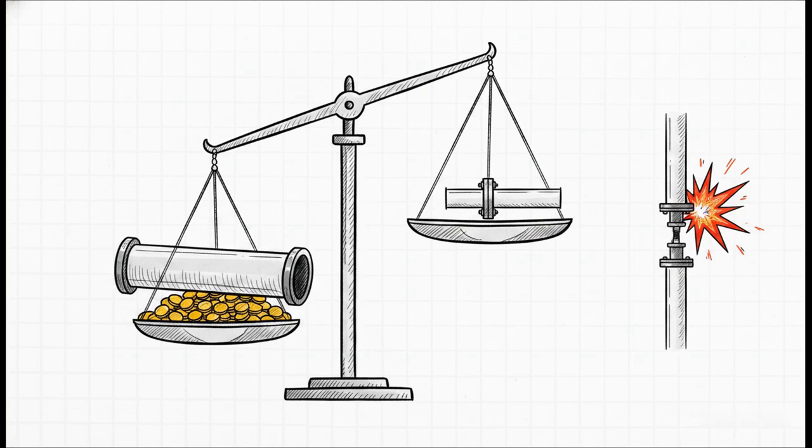Second is practicality. You simply cannot gold plate every single line in a multi-billion-dollar process plant. The project economics would just collapse. Third, it reflects the true code intent for pressure design. The pipe class should mathematically match the pressure it will actually experience under worst-case credible scenarios, not the absolute highest pressure anywhere in the entire facility. But listen closely to this trade-off. A spec break is only free money if it is placed correctly. Downgrading downstream piping saves significant capital cost, sure, but incorrect placement creates a catastrophic weak link in your system that can literally rupture under pressure.